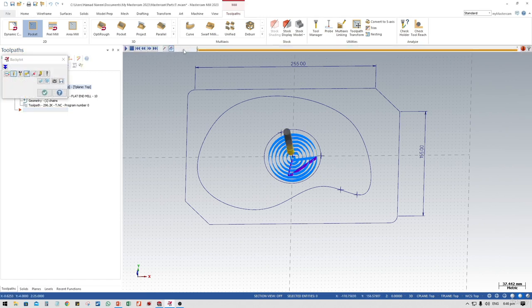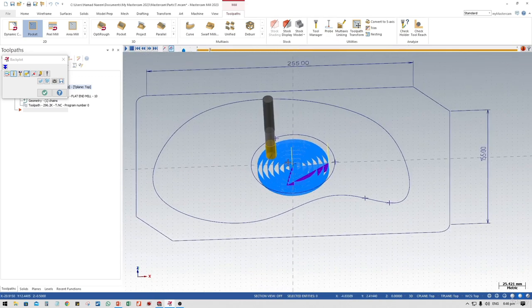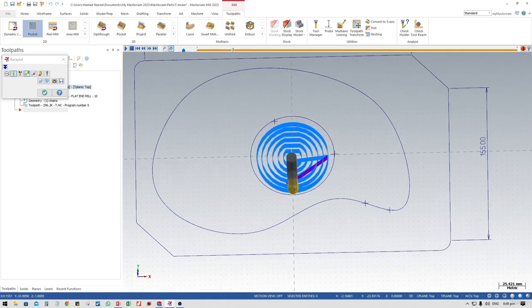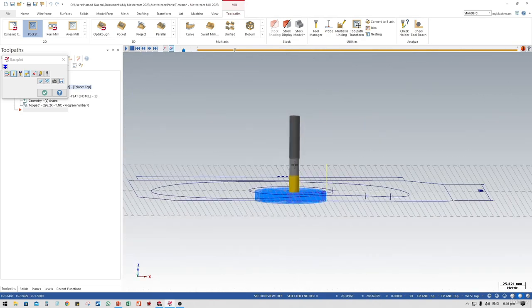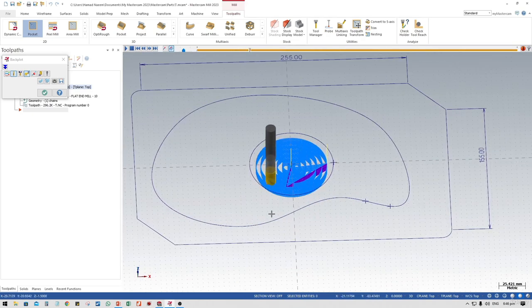We'll make it slow speed, and this is how the cutting tool works, in a spiral way, a constant spiral method of cutting, and it will go from 0 to minus 10mm in a downward direction. So I just showed you how we can select the geometry by using the chaining manager tool.